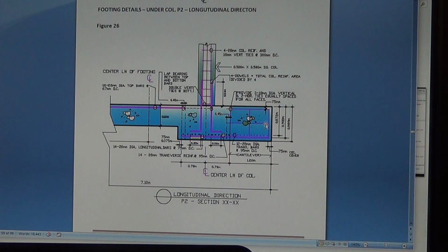But how about here? That's why, according to the code, thanks to the building code, when a beam is more than 36 inches, more than 3 feet, you have to provide two horizontal web reinforcement. If this is like 3.5 feet, you have to have two here, two horizontal web reinforcement. Web reinforcement means stirrups. This one here is vertical ties, vertical